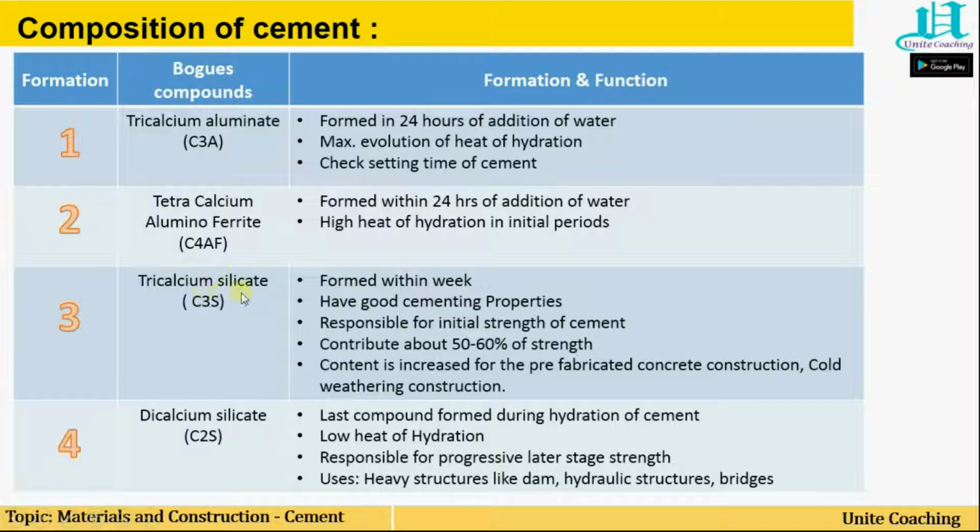Then comes tricalcium silicate. See, it takes a week, or within a week it is formed. C3S. It has good cementing properties, it is responsible for the initial strength of cement, and it contributes about 50 to 60% of the strength.